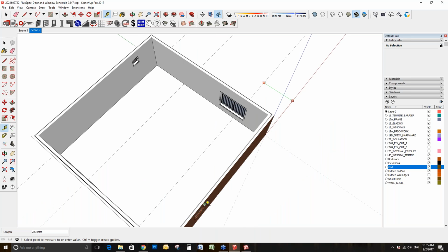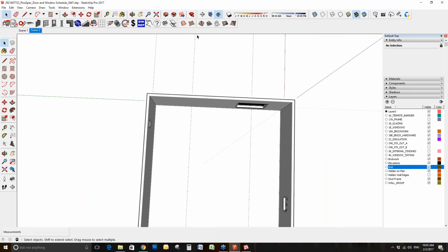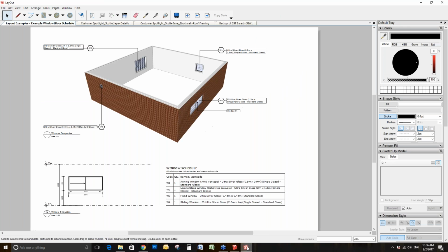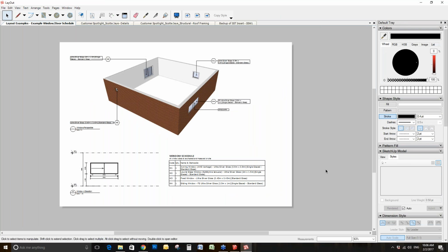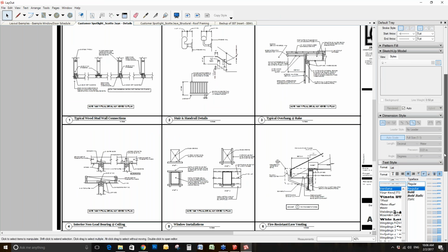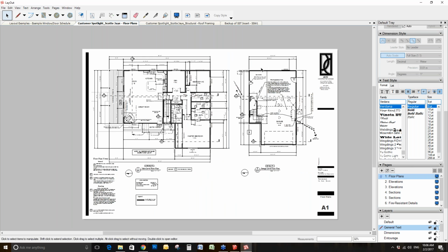Now, when you go into layout, you're just going to ensure that you can see this layer. So when you go into a ground floor plan, make sure that the grid layer is activated and it's not hidden. And then that way you'll know that you can actually use it, which means inside of layout, you can simply, at the end with the grid line, if we go into here, you're simply putting in the element that you want to use.